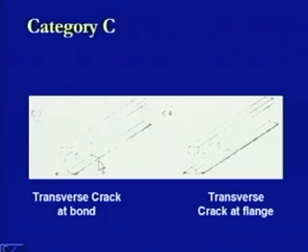That same thing can also happen from the bottom. Here it is happening from the bottom and is going towards this fish bolt hole. So, it means there are more stresses which have been induced at this point, and therefore it is getting cracked in this location like this. Then the transverse crack may be at an angle instead of at a perpendicular condition. This is another form.